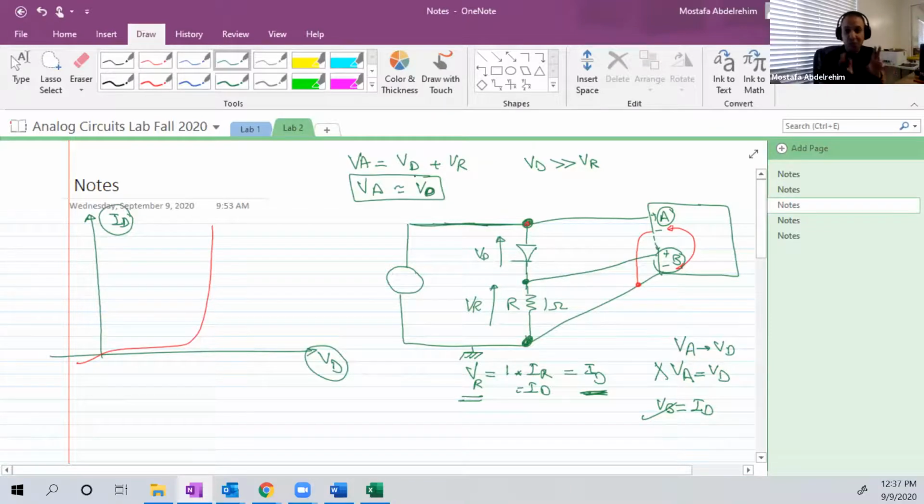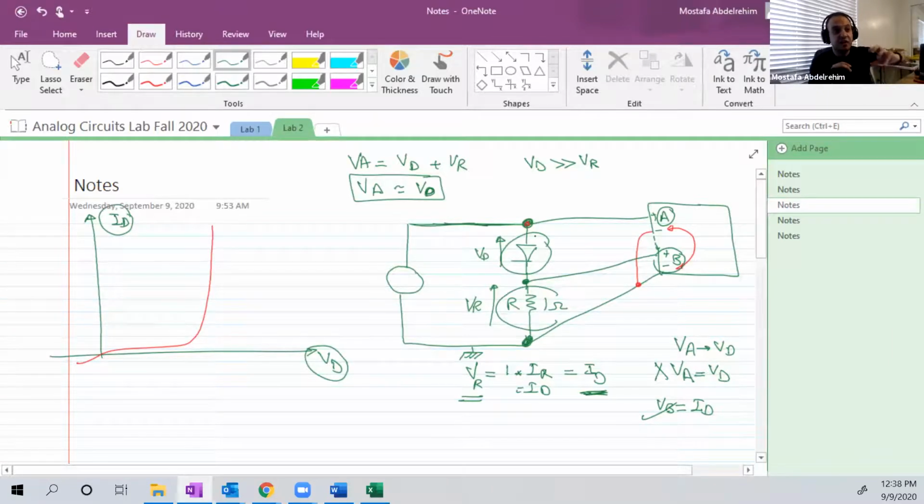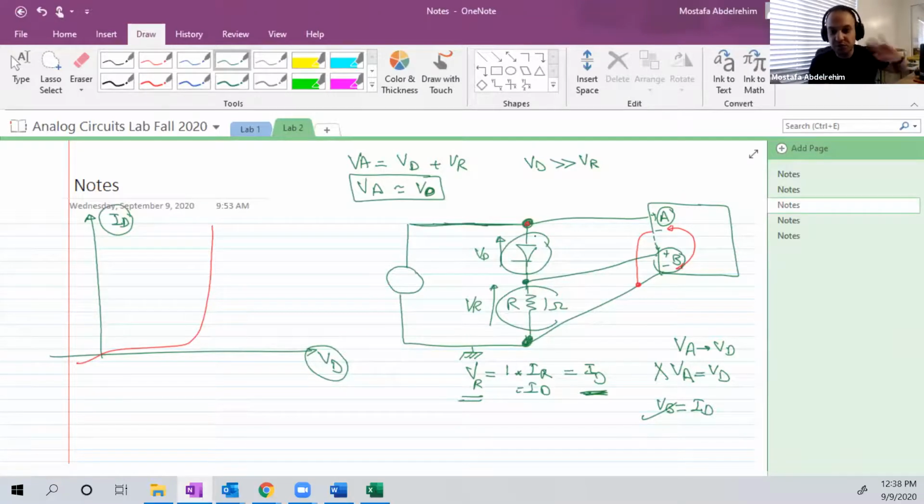We have two devices now. We have our resistance, which we will consider a device for now, just between us, and we have our original device, which is a diode. If we know the resistance of the diode, we can choose R to be much smaller than the resistance of the diode, so that its voltage will be negligible compared to the voltage of the diode.